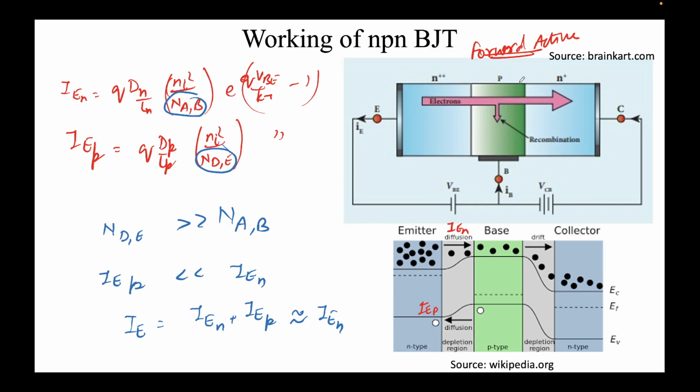So you see, that's why in this picture, if I dope during the fabrication of this device in such a manner that I have the respective dopings such that the primary current is due to the contribution of electrons and very minimal is coming through holes. We do not want that. And as I've already told, if you have low doping, that also benefits in that there'll be lower recombination in the base.